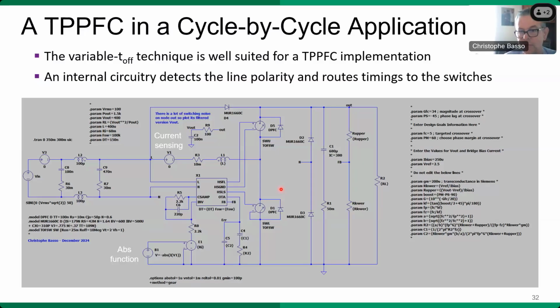Rather than starting from scratch with very complicated SPICE models of everything and then it doesn't work, you don't know who is the culprit. Starting small and then increasing the complexity and the comprehensiveness of the models is the way to go if you want to have, let's say, a well-running simulation and not lose time in debugging the circuit. So here, this is the TP-PFC.